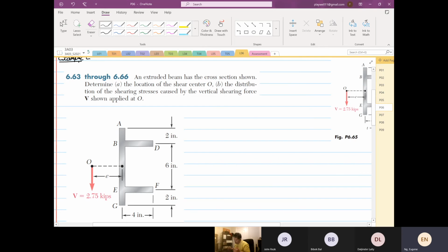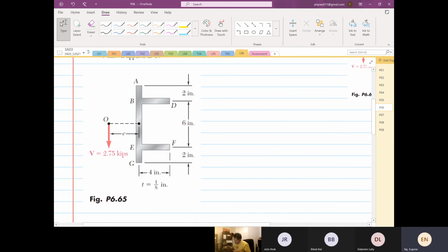Okay, so the thing that is not the most difficult but confusing is how the F1 and F2 will move. So that is dependent on the Q. Okay, so from here we apply rule number 5. Remember rule number 5, that the shear flow is controlled by the web. Right, we know this. So this is our Q, our shear flow.